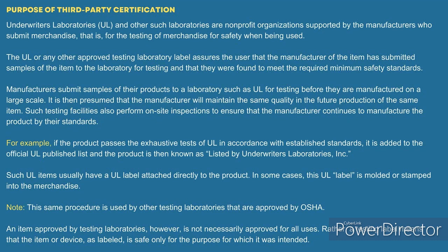But I'll tell you another. Especially how they mention that if you cord and plug connect it, you have to comply with Code Making Panel 2. If you hardwire it, you comply with Code Making Panel 12. Sure. And that supplements or modifies Chapter 2. Yeah, I agree.